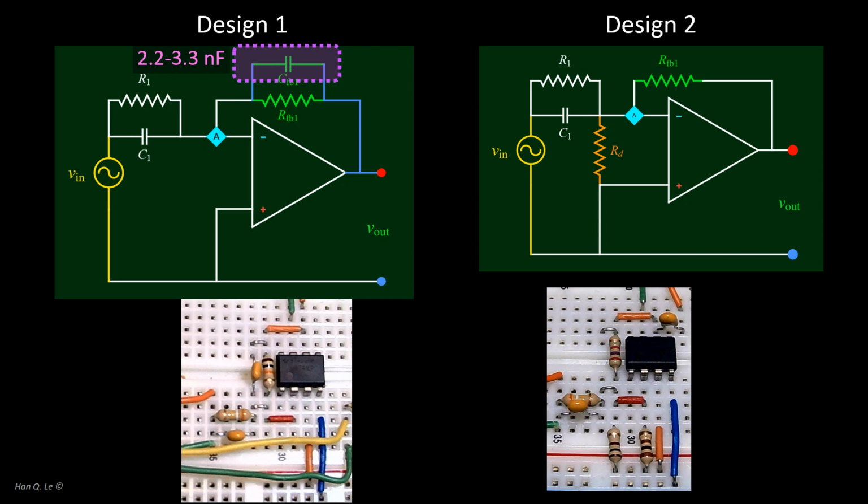If you don't have the components for design 1, consider design 2, in which a dampening resistance value of 47 or 50 ohm is needed. Many without sufficient capacitors have chosen this design in the past. Both are adequate for the experiments of Part B.